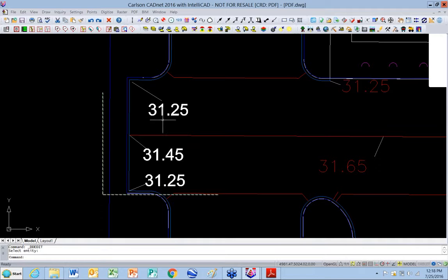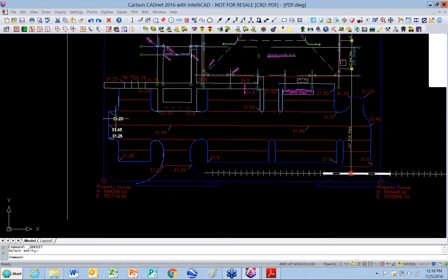And if later on I wanted to elevate, I would use the civil module, and there's 2D to 3D polyline in there that allows me to elevate it into 3D. That'll be in a different webinar. But on this one here, I'm just showing you how to take a PDF file in and then convert the polyline text into actual text to use in CAD.